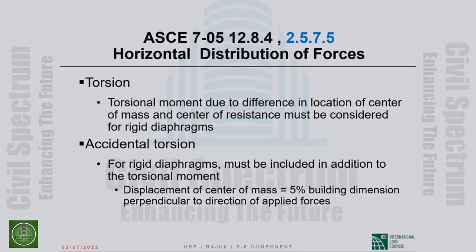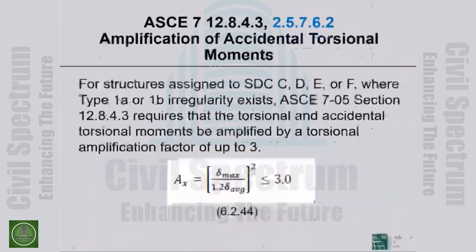Now, there was a time, a long time ago, when we used to design for the actual torsion subject to a minimum of the accidental torsion. But those days are long gone. We have for a long time been designing for the actual torsion plus the accidental torsion. Not only that, the accidental torsion many times has to be amplified.